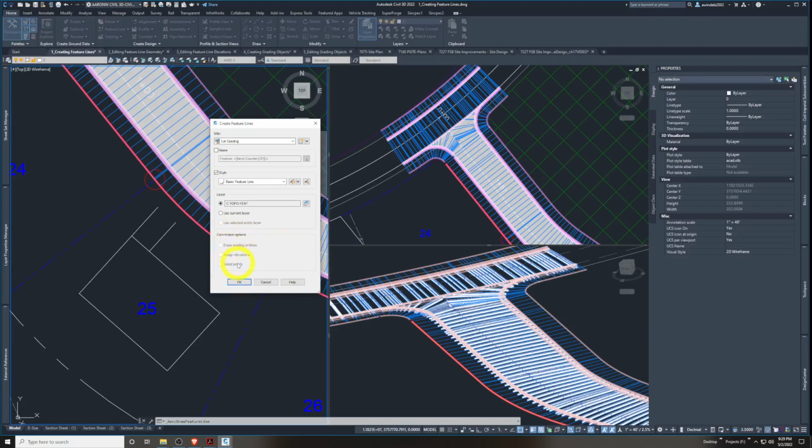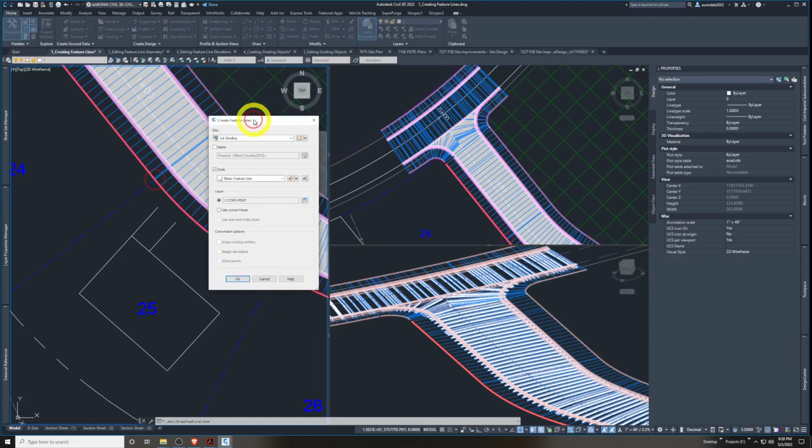Like I said, we're creating this from new, so these aren't options, but weeding points would say, hey, I want to create this feature line that crosses all these TIN lines. It'll make all these intermediary points. You might not want that, but in this case, a little above and beyond, but this is a typical dialog box when you create a feature line. We'll hit OK.